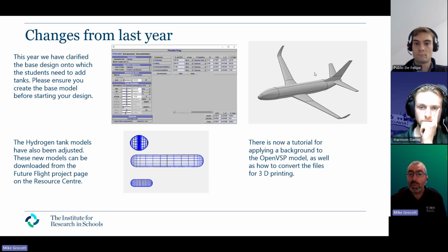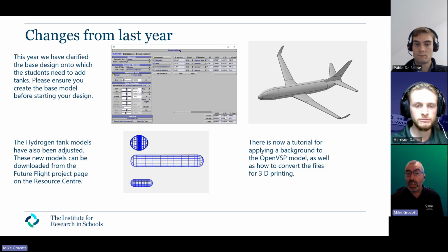So when you've got your model, you have to hide the nacelles and all the other bits and pieces. So you've got this design here, this very clean skin of a 737. This here are the figures. So these are the parameters that you need to make sure you've selected. You run a calculation, and that will give you your baseline CD. So that's without anything added to it.